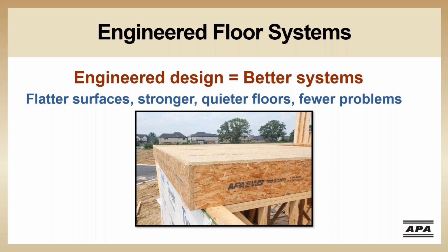The I-joists and subfloor, when properly glued and fastened together, help eliminate the independent movement of the floor system components. And that independent movement is what creates noises like squeaks and also uneven floor surfaces. Positive connections of these components are going to result in reduced callbacks. And that's not only a headache for the builder, but it ultimately impacts the profitability of the project. APA does recommend both glue and fasteners to attach the floor sheathing to the floor joists.